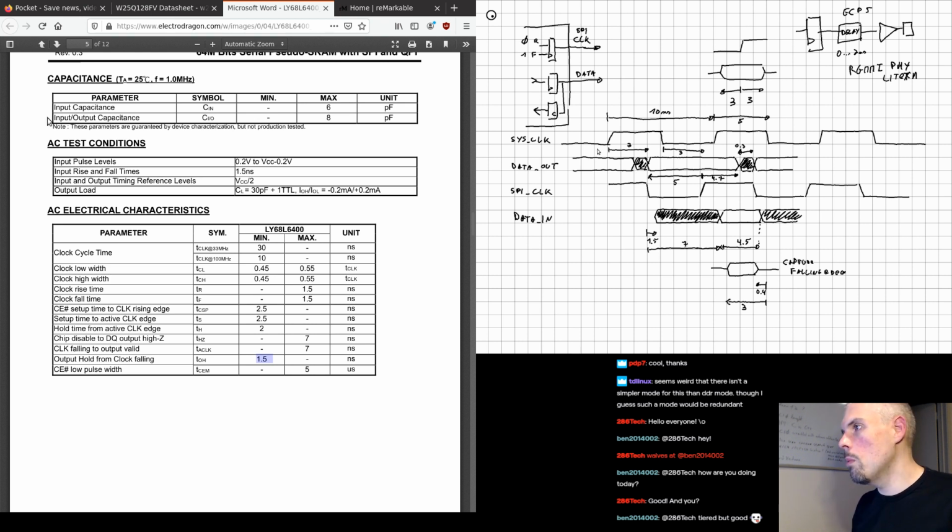Sometimes the whole latency of the I/O pipeline, from the output register to the device, then back to the input register, can easily be 3 cycles. You have the passing of the first clock, then the device responding to your clock edge, which adds one more cycle, and then actually sampling it in the I/O register. You only get the response from the device 3 cycles after, which in the case of SPI we don't care about because we read data. We just need to capture it a little later. There's no loop or feedback requirement like that, so that's not an issue.